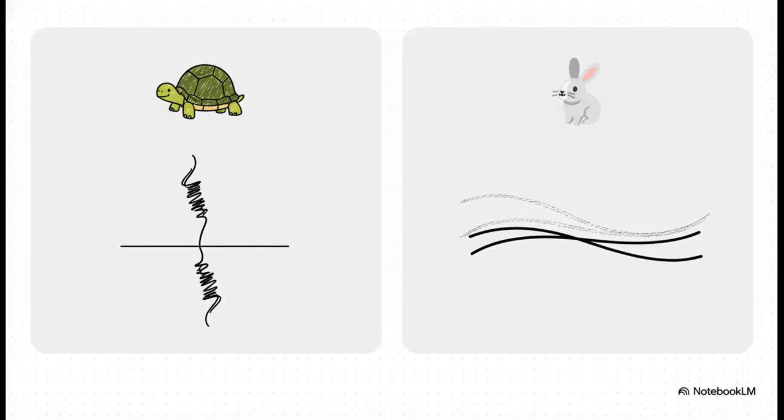Let's look at the biggest difference, single lift versus double lift. The early single lift Dobbies were pretty slow, and they were really tough on the yarn because they had to bring every single thread back to the middle after each pass. But the double lift design, that was a total game changer. It could run way faster with a lot less stress on the yarn, all because it could hold some threads up while moving others. This created what's called an open shed, and this is the design that really took over the industry.